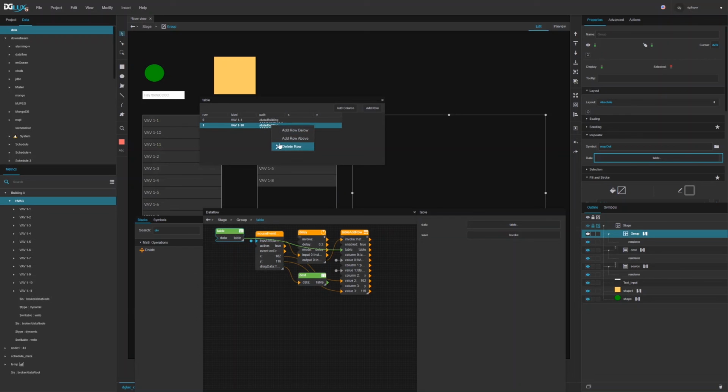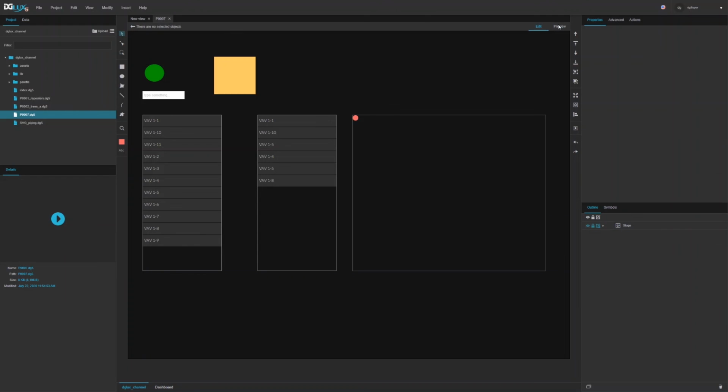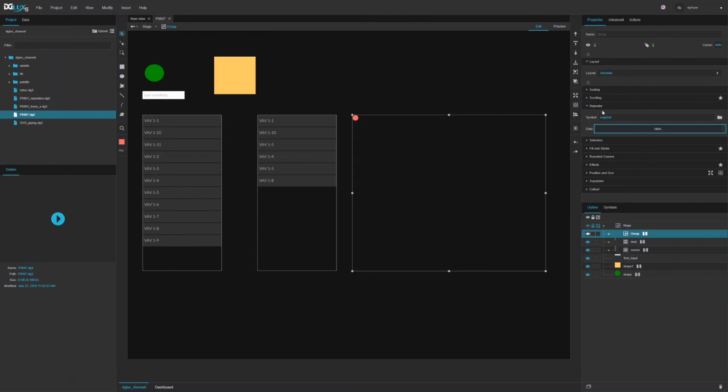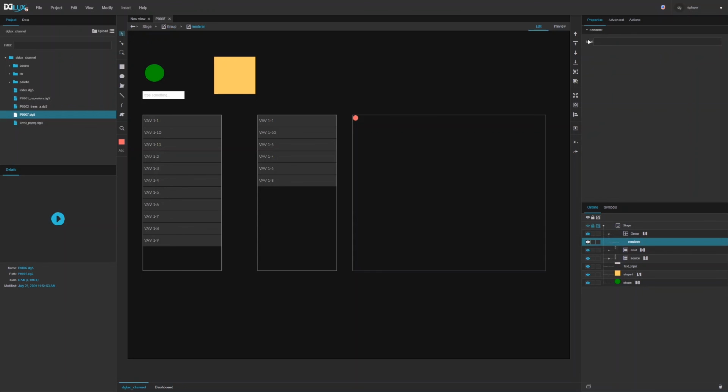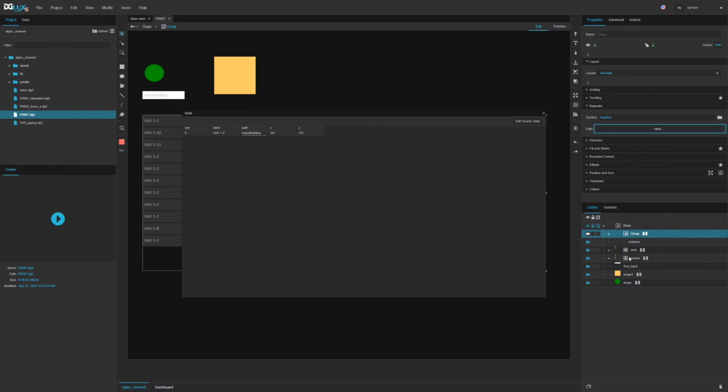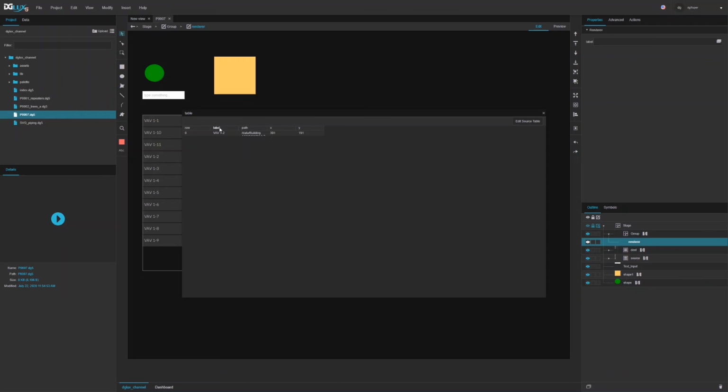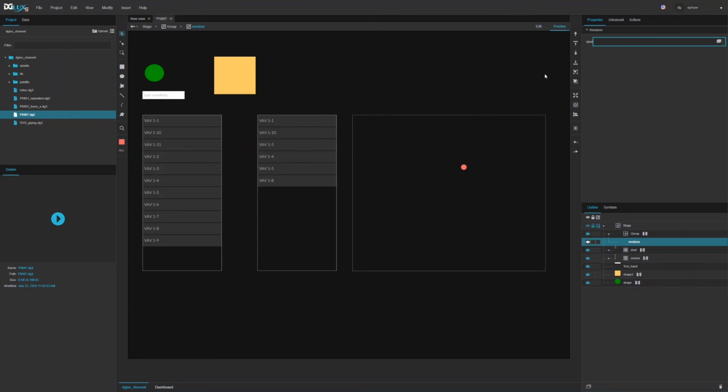Of course, we didn't take time here to set up functionality to remove items because that's not part of the lesson. All right, so there's just one thing left to do. Remember, we created a label property, which is not bound yet. And because not a single property is bound to the repeater table, the map to table block inside the symbol will also not return your row. It's very important to have at least one property be driven by the table. So I'm going to bind the label. There we go. So that made everything work, and on mouse over, of course, it gives me the name.